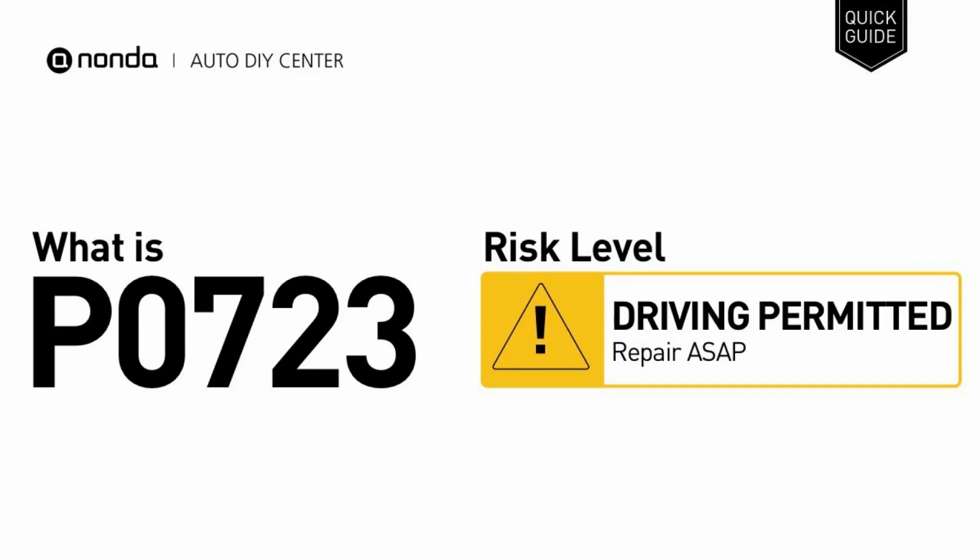Transmission fluid temperature sensor. A faulty transmission fluid temperature sensor, TFT, can also be the cause of error P0723. This is usually seen in vehicles equipped with the TFT sensor installed in line with the OSS sensor. The TFT sensor is also checked for resistance using a multimeter mounted on an ohm scale. If the reading is out of specification or exceeds the limit, replace the TFT sensor inside the gearbox.